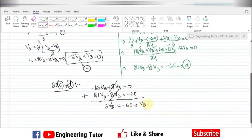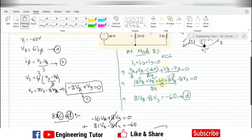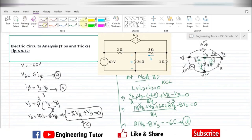Now as I have both equations, let me solve them. The value of V2 would be equal to minus 12 volts. Now we have to find the value of small v1, which is here. In order to find it, we should have the values of the two potentials at the ends of this 24 ohm resistor. So we know the value of V1.